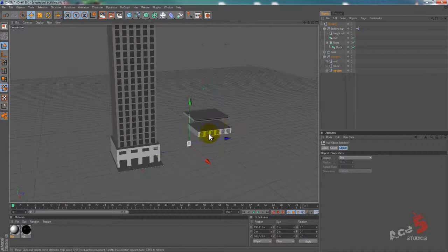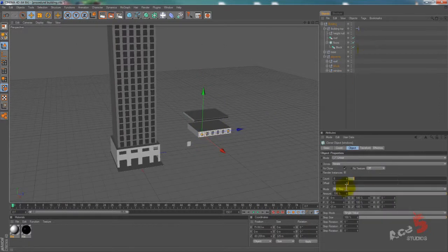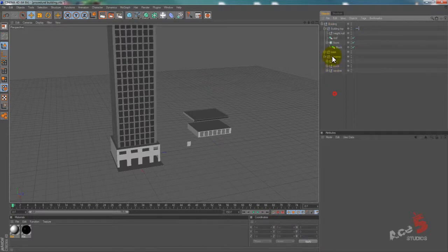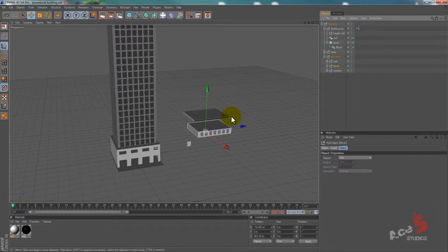Say if I want to have more, see 7, and then I want them to be closer packed, I only change it on this object out here, which I can copy into a new scene and give to a modeler or something, and then he'll model the facade. And then I'll just plug it right back into the null object right here.